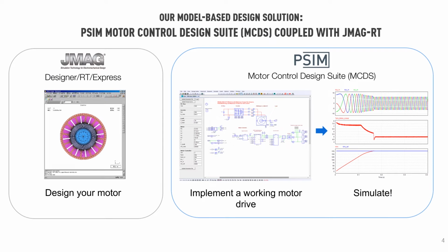The Motor Control Design Suite in Psim makes all those tasks very easy and helps users save time. Based on minimum system specifications, the suite automatically designs all the controllers for speed and current loops with proper specified crossover frequencies and stability margins, and with advanced control algorithms such as maximum torque per ampere, MTPA, control, field weakening control, and maximum torque per volt, MTPV, control. It will generate a complete system that is operational and ready to simulate in a few minutes.